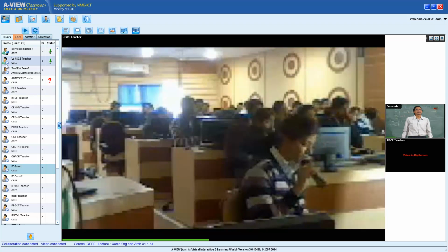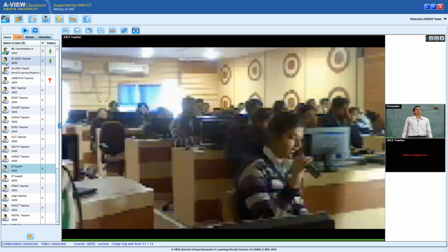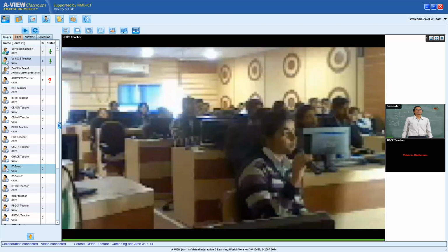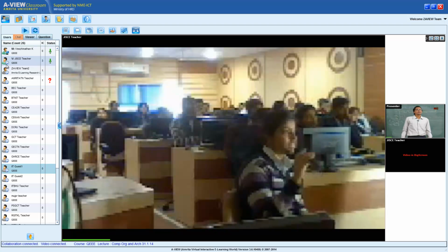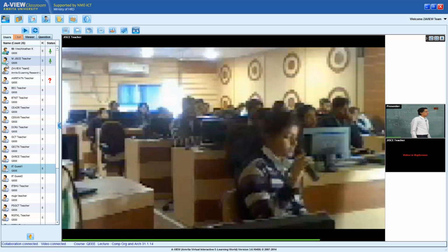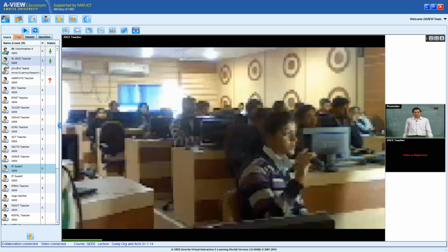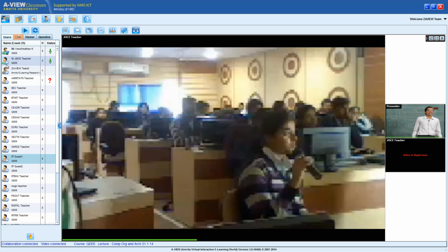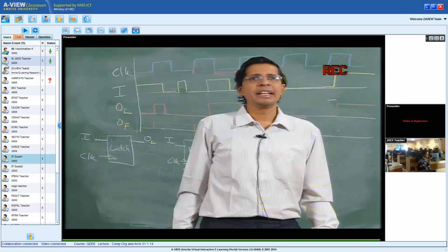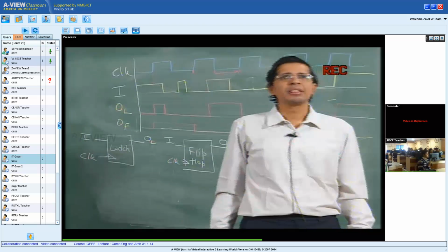Now, what will be the number of inputs and outputs for comparator, adder, multiplier, and divider? See, for example, if I am comparing two 8-bit numbers, in a comparator the total number of inputs would be 2n bits and the output will be 3 bits.